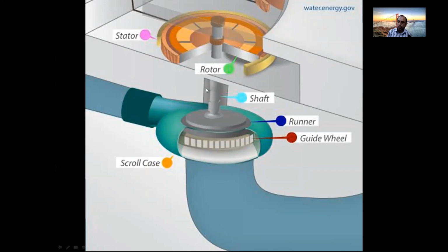When the turbine is rotating, it rotates the shaft, the coupling, and in turn the rotor. And outside the rotor there is a stator. By rotating that coil inside a magnetic field, you generate electricity. Generally, that electricity is low volt and high ampere. It is then taken to the transformer hall where it is converted to high volt, low ampere. Power remains the same, except for some losses during transmission.